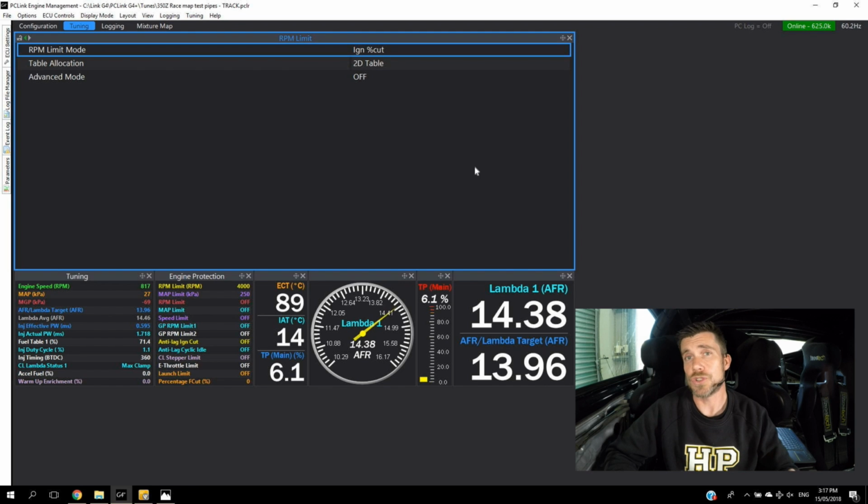With our old drag car, we were running an HKS T51R turbocharger, which is a 1000 horsepower rated turbo on a Mitsubishi 4G63, which is a 2-litre engine. Now, if you were just to hold the engine on a normal fuel cut rev limiter with no ignition retard at, let's say, 7000 RPM, you would probably get maybe 2 or 5 psi of boost. Very little boost, certainly not enough to launch off the start line at a drag strip.